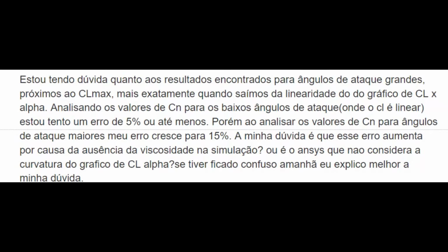In case of separated boundary layer, this definition of characteristic distance from the wall does not work, and it breaks the turbulence model completely. And in this case, we can also observe high error, but not always it happens. In some cases, it will not be visible. So it depends from one case to another, from one airfoil to another.